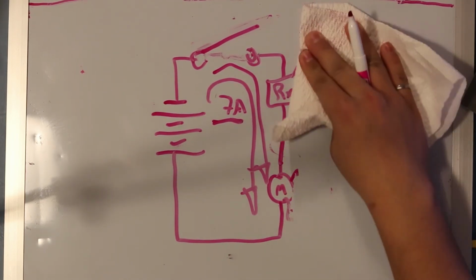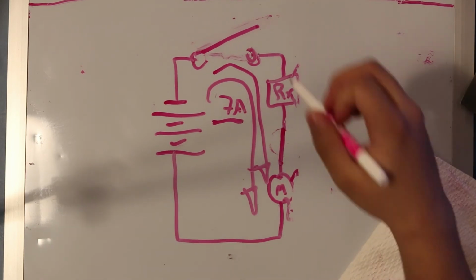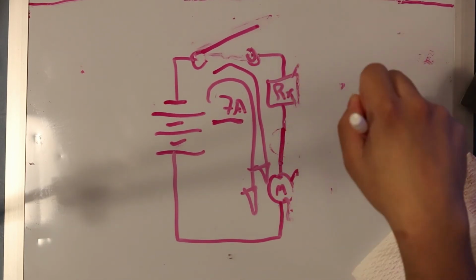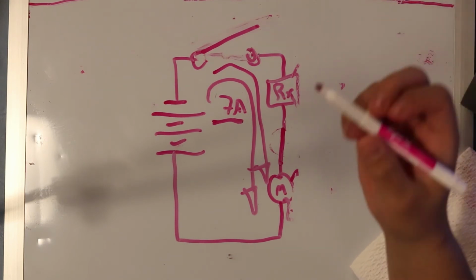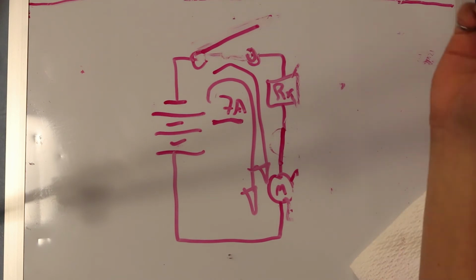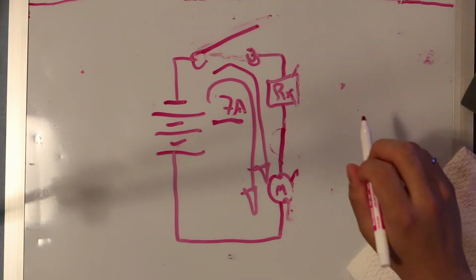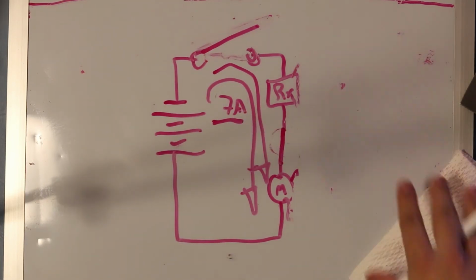These disconnect switches are very important, and it's in the scope as well too, because they're a safety device and they need to be as visible as possible. That's why we tell you in the scope, make sure your disconnect switch or any breakers or anything like that are visible so that the judges or anyone else can go over to the robot if it's going crazy and just flip a switch and turn it off. That's one way to do it.